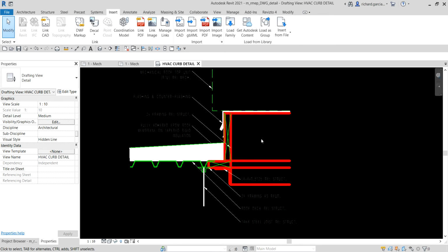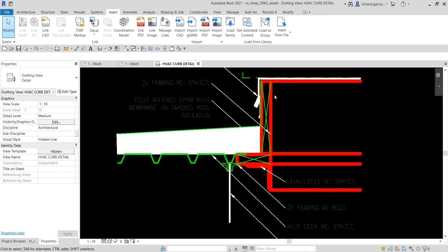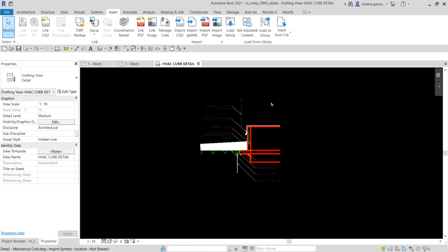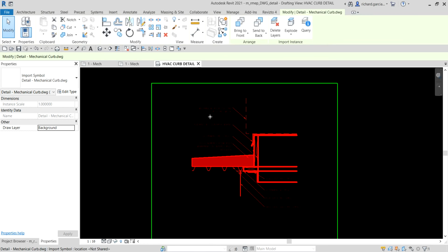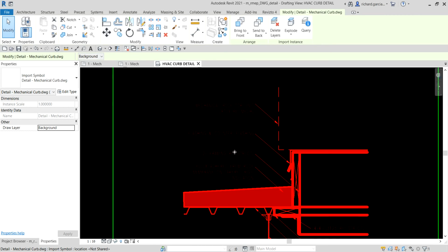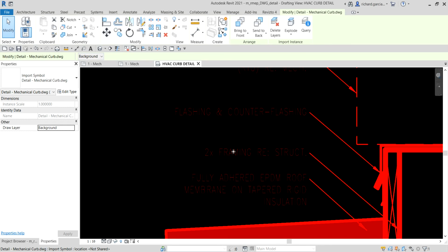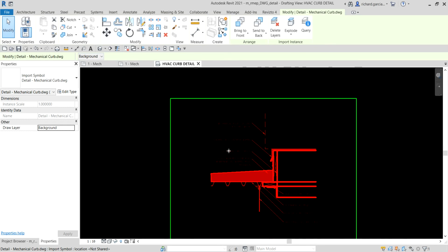And there you go. So as you can see, that is another way of editing your drawing. I'm just changing the color so that you'll be able to see where that particular element is that I am modifying. Now another way is you can actually explode this, because as you can see, if you click that, let's say there is a wrong spelling on the AutoCAD drawing, you cannot just double click it and change it, right? So you need to explode it.